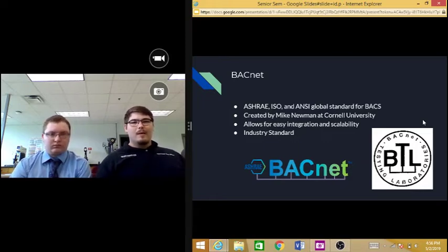BACnet. I always talk about BACnet, and the reason is because it's absolutely crucial for developing a system like this. BACnet was developed at Cornell University, so luckily I had access to the information for creating a system like this. It's an object-oriented language with services running similar to commands. It gets complicated. You have to create these huge tables of different objects. Each object can represent an analog input, analog output, digital input, digital output. But this is something that is absolutely crucial in order to create an actual system that could be installed into a building.